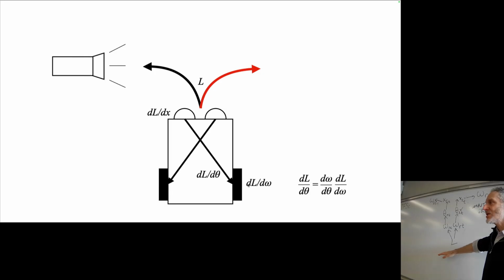So this computational graph, remember, we're working backwards through the simulator. What do I mean by backwards? We start with loss. We go to the speed of the wheels, which was what affected this trajectory. Instead of sense, think, act, we're doing act, think, sense at the very last time step of the simulation. Then we go backwards again.